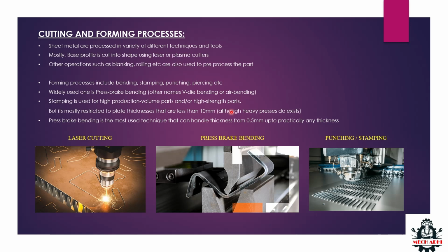A lot of manufacturers have laser cutting capability. And then coming to forming process, we can divide it into two, which is press brake bending, as I pointed out earlier. Press brake is the most conventional way of bending. So we have a V die, and then we have a press here. That's a tool, and then we keep our sheet metal, and there will be some stoppers to indicate the limit to which your flanges can extend out, so that we have a precise bending.